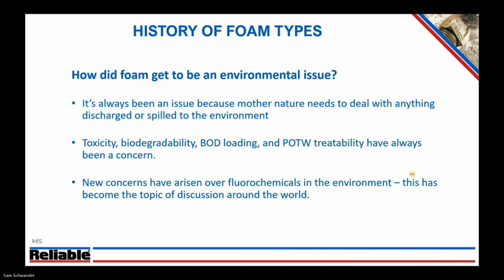So toxicity, biodegradability, BOD loading, so biological oxygen demand loading, and then treatability at the local POTW. Those things have always been concerns. And then, over the last few years, the use of PFAS has really been looked at, and the industry is moving away from that sort of chemistry.